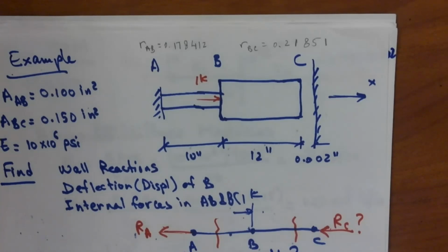So it's not made of structural steel. And we want to learn how we can model this part and create it as a 3D geometry in ANSYS. And once we do that, we should be able to create geometry, assign material, generate a mesh comprised of solid elements, define the boundary condition, apply the loads, look for a solution, define results, and know how to get everything we were looking for.